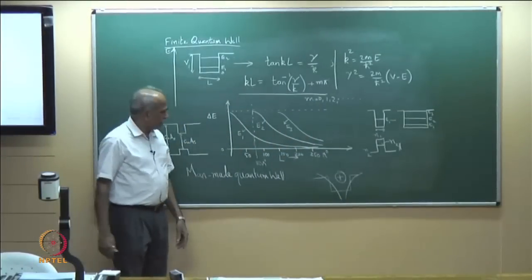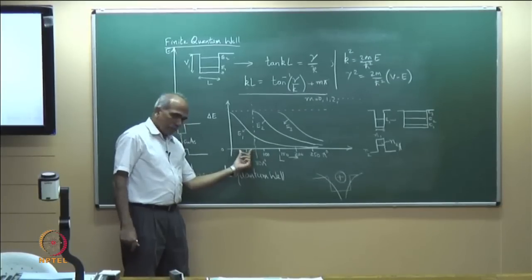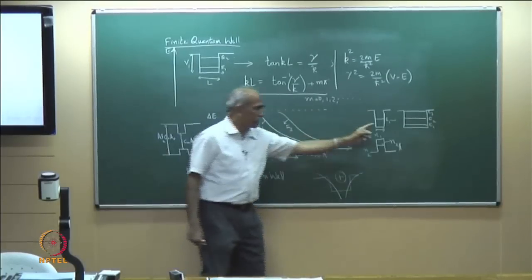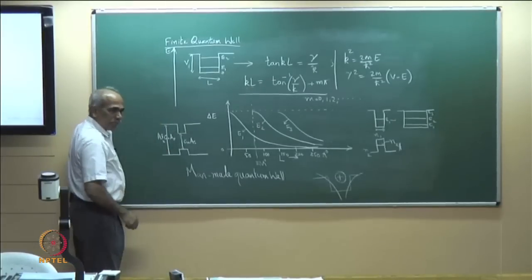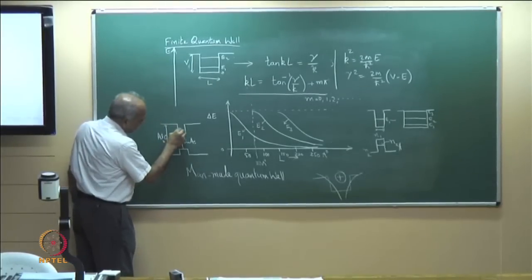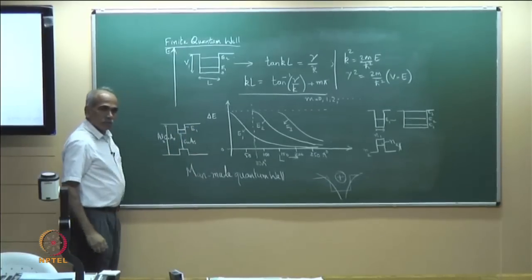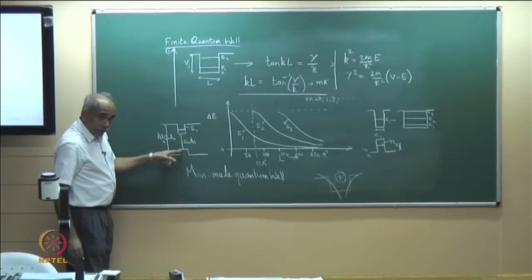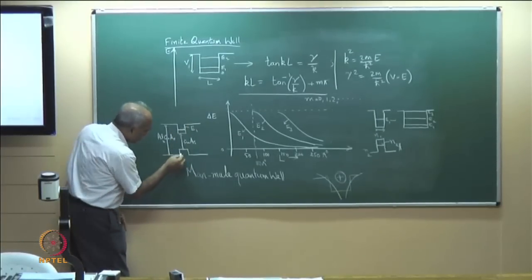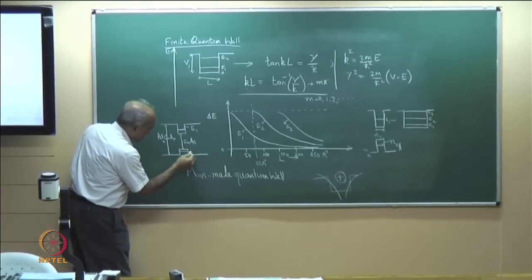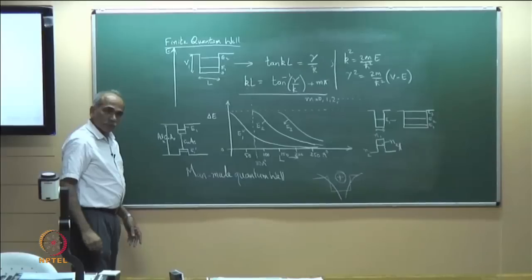So, we come back here: over this range, if I vary the width, the energy eigenvalue changes, which means, coming back to the well here, E1 is here. Similarly there is a well here, it is a barrier for electrons or a well for holes, which also has energy eigenvalues, which I call E1 dash for the valence band.